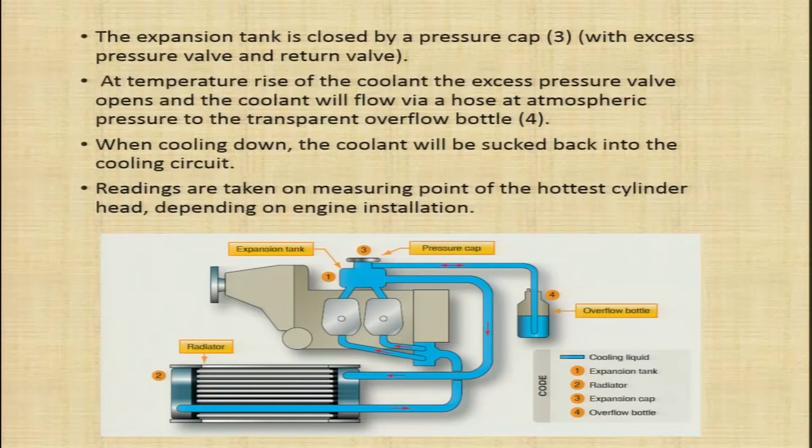The expansion tank is closed by a pressure cap. You have a cap here which is a pressure cap. This pressure cap has an excess pressure valve and a return valve. At temperature rise of the coolant, the excess pressure valve opens.